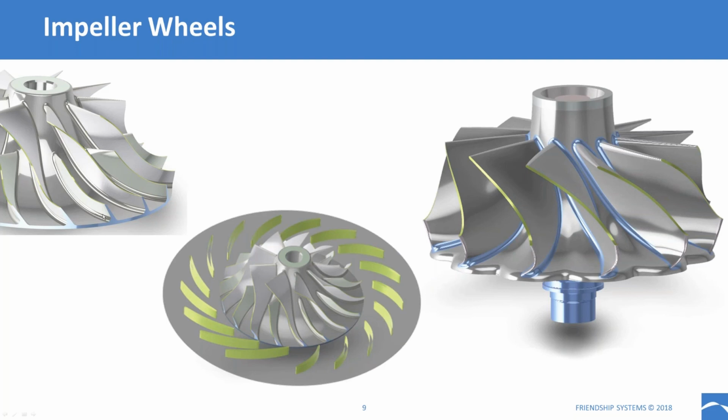So you can do very complex geometry modeling inside of CAESES of these rotating geometries, but also of volutes and things like that. And I think you asked about the comparison to CF Turbo. I think some things are maybe better than in CF Turbo. There is more flexibility in CAESES, and the way things are parameterized is better for the optimization. You can include more details like the filleting and the end wall contouring, as well as the hub or the shaft that you see here in the picture.